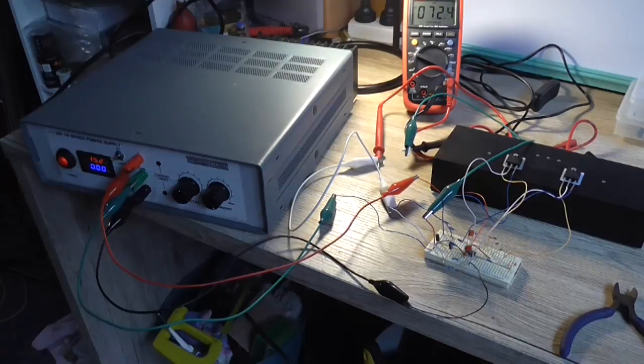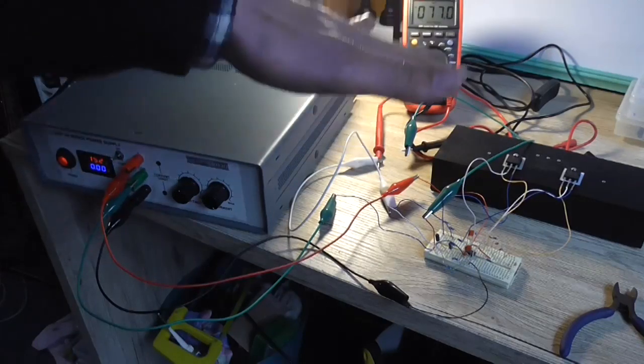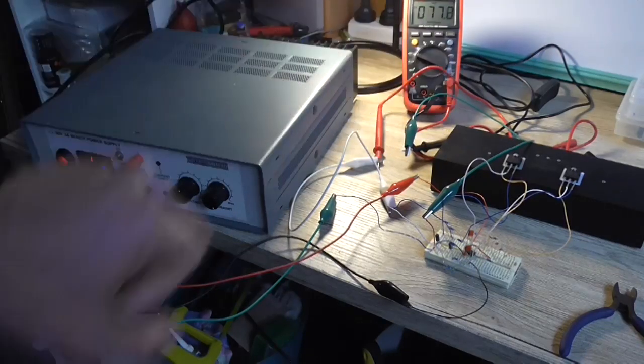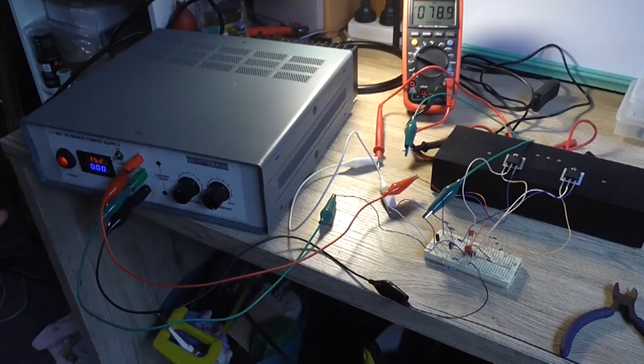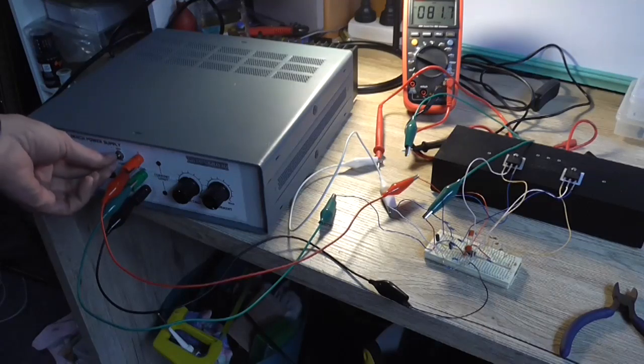They're rated at 250 volt, 15 amps, something like that. So for the low power that we're working with, it should be fine. Now at the moment the output is unloaded bar the multimeter. So if we suddenly see a jump in current, we know there's a problem. So I'm going to turn it on,